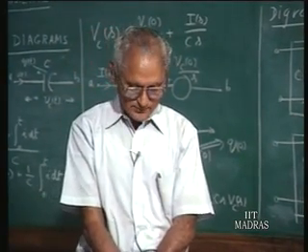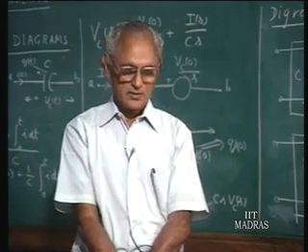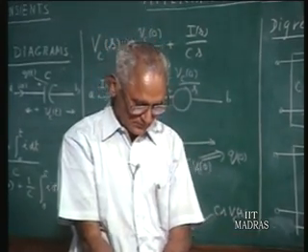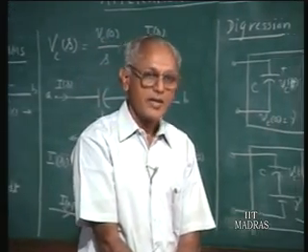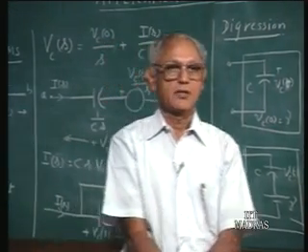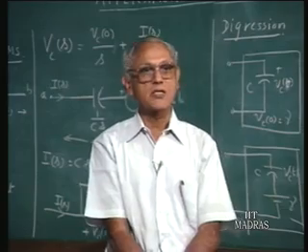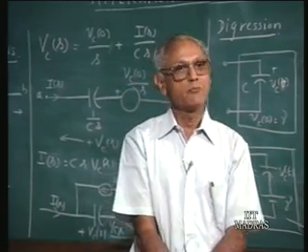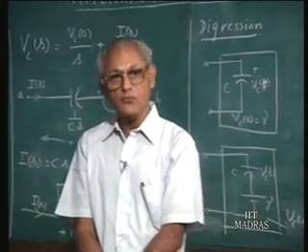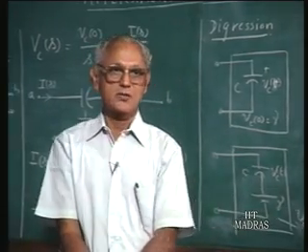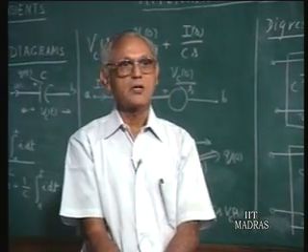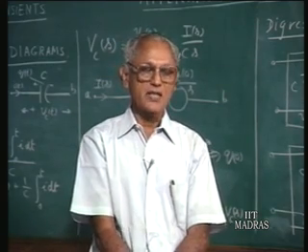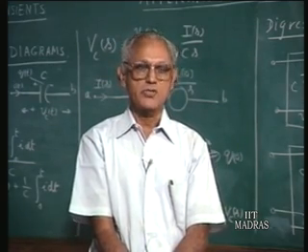After having said that, we know that in transient problems some switching takes place, let us say at t equals 0, and we are given, or at least we can find out, the conditions in the circuit before the switching operation takes place. That means 0 minus conditions are known to us in most situations. Therefore, it will be convenient to substitute 0 minus conditions, and the solution that we get will include the transition between 0 minus and 0 plus.